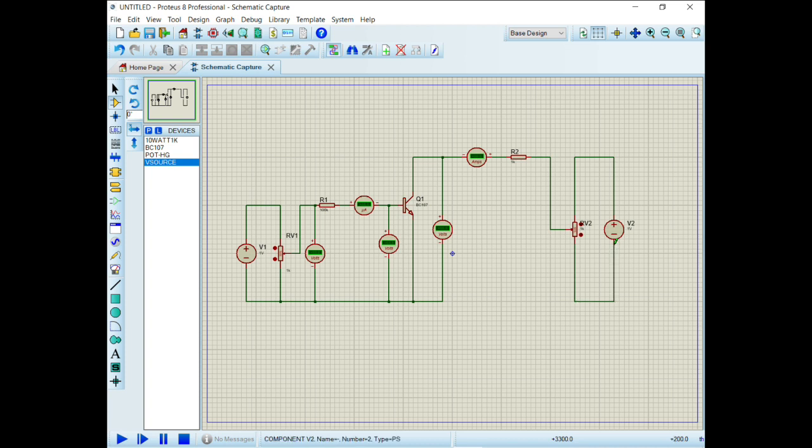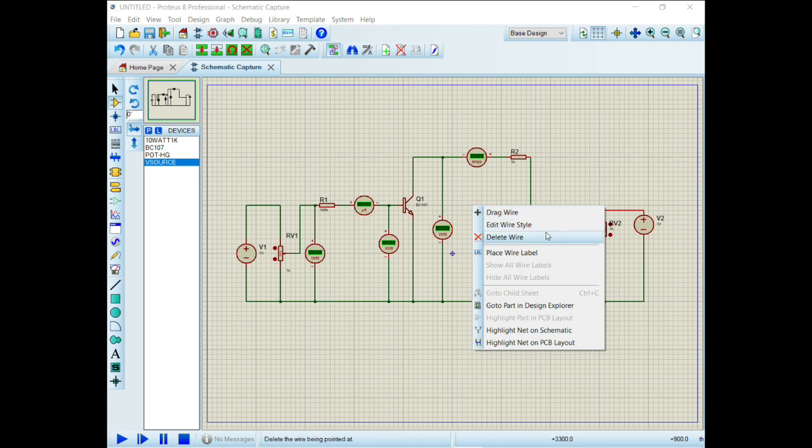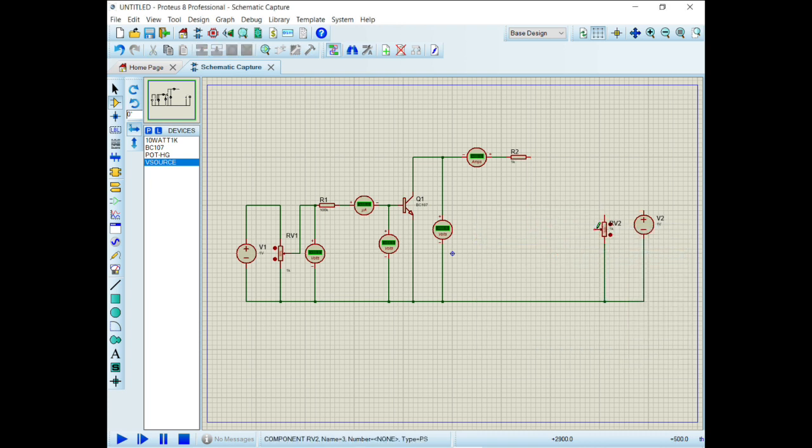You will also be interested in checking the voltage that you are varying. So you will require a voltmeter around this area. Remember that you'll have to connect these two because all of them are grounded. So I'm going to push this a little bit to the side so that I can add a voltmeter to measure the voltage VCC.